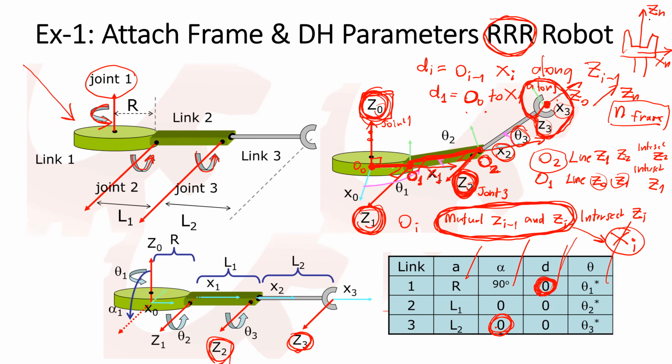The first way is to point the Z axis outward from the gripper direction and have the X axis in the direction of motion of the gripper. The gripper moves out and in, right? The X direction can be here. Or the second possible choice, just put the Z axis with the same direction as this. It's also possible. So in this step, we know how to attach frames.